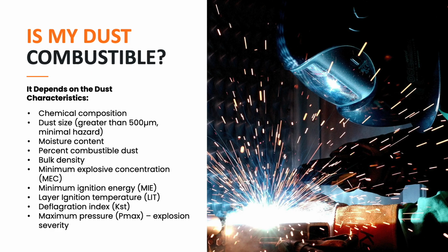But the important takeaway from this slide is if you're not sure or you think you have combustible dust, you must, to comply with your requirements from OSHA and other requirements, go get a DHA lab test done. They'll send you back a report and they'll tell you if it's combustible, how combustible, and they'll give you all of those important values to determine what are the next steps of your process.